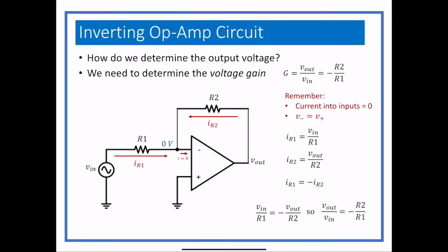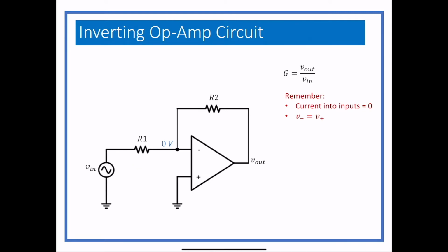We call R2 the feedback resistor. It will occasionally be marked as RF. Sometimes it is, sometimes it's marked as R2. So don't get fooled into thinking that you use what's labeled as R2. Just whatever the feedback resistor is over whatever the series resistor is, that's going to give you that value. So now that you have memorized that one, hopefully, we're going to do something else.